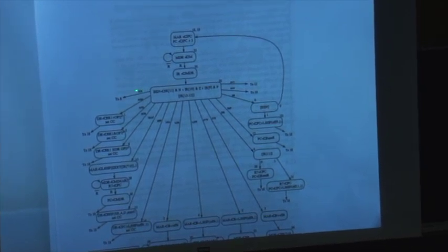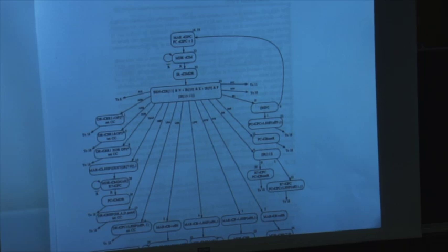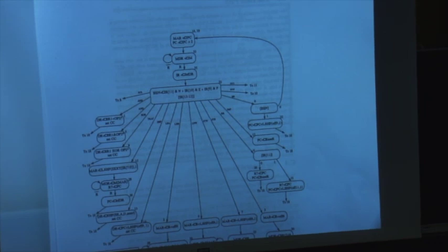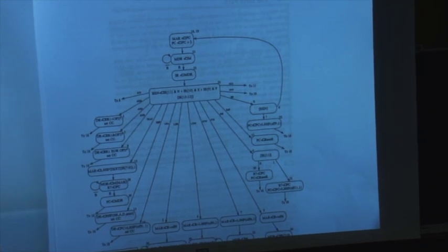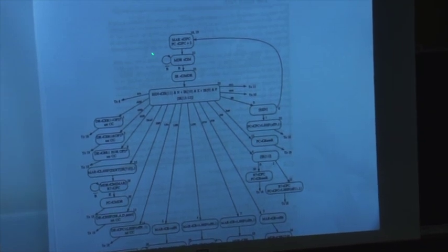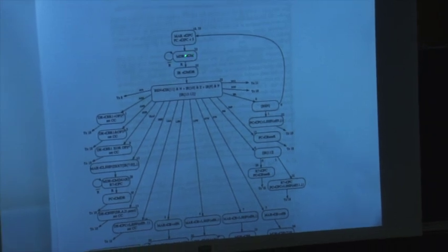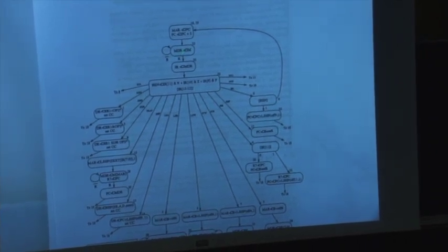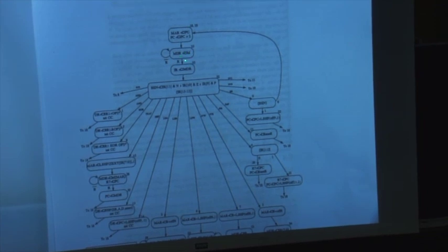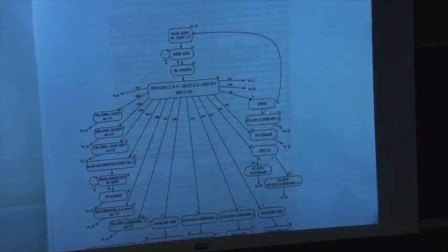This is actually a return from interrupt. So there's something that happens. Ignore these instructions that do not go to any states. So it's actually 1, 2, 3, 4, 5 states, right? Fastest instruction. But that's not the same thing as cycles, though, right? Because you have these conditional transitions. So assuming your memory takes 5 cycles, then the fastest instruction takes 1, 5, that's 6, 7, 8, 9 cycles, right? Okay. How many cycles does the slowest instruction take?